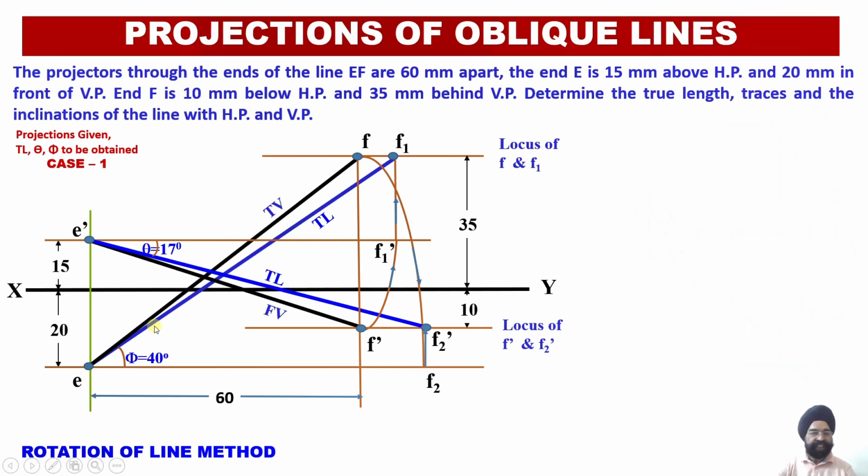So this way, please check this out. Once again I repeat, this will be H dash over here, and this point will be H. Similarly, this is EF, and wherever it intersects this XY line, this point's name will be V. So here V dash will be obtained. V lies here because EF intersecting with XY gives me V, and at the top of it, where the vertical projector intersects the elevation projection line, this gives me the point V dash.